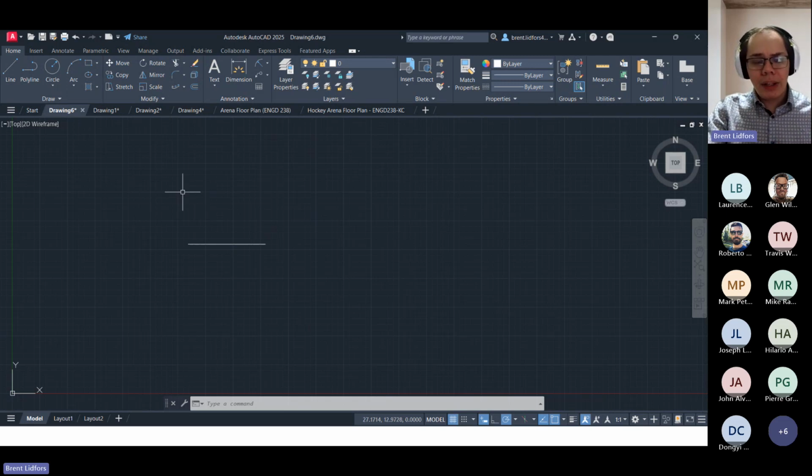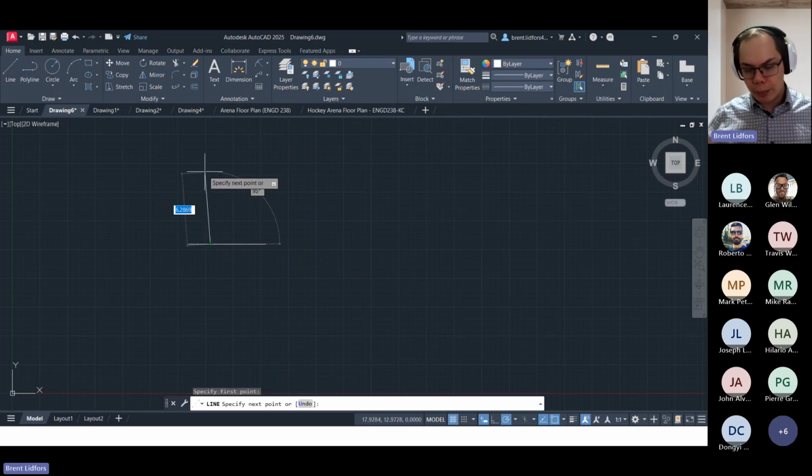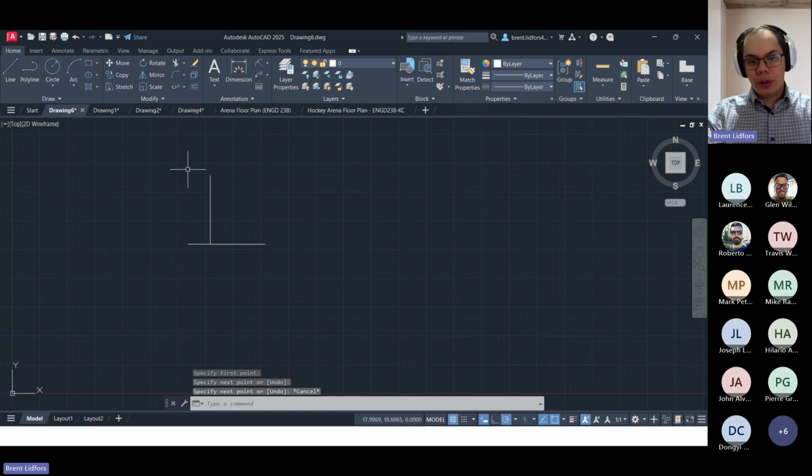Then I might use something like break to give me that accessible object snap for later purposes. If I use break, I can select the object, use my object snap tracking, enter 2 units away from that object snap, hit enter, and now I have a reliable endpoint snap that could be used to branch away from that break. So I can draw off of it.